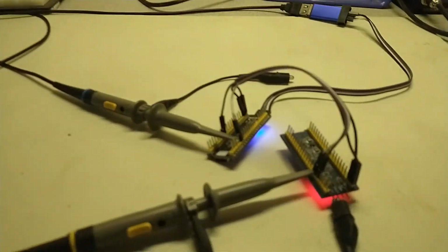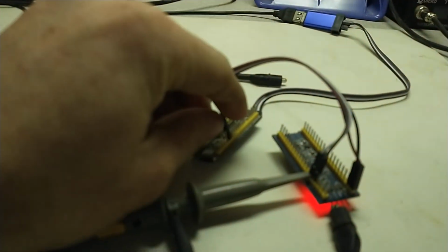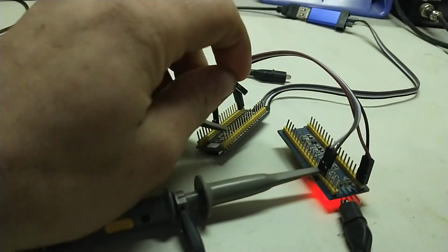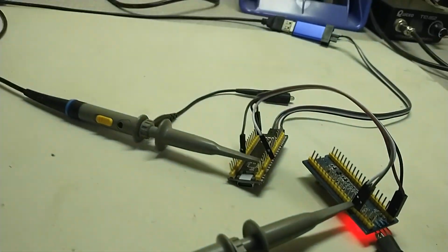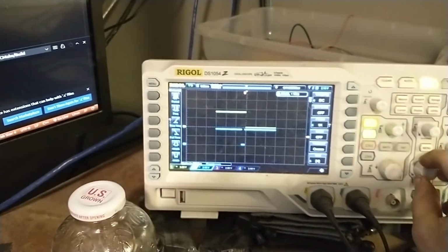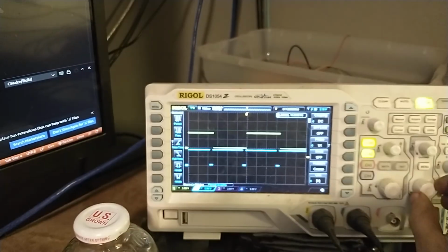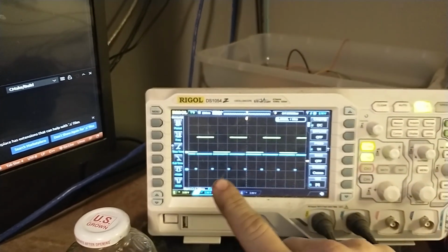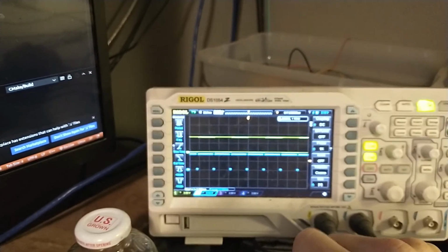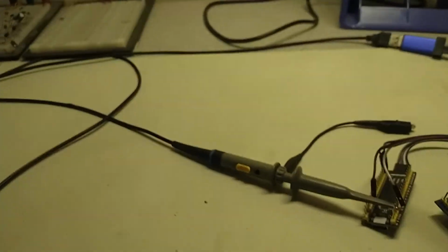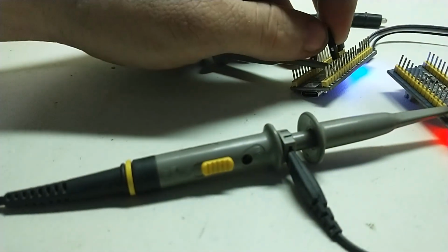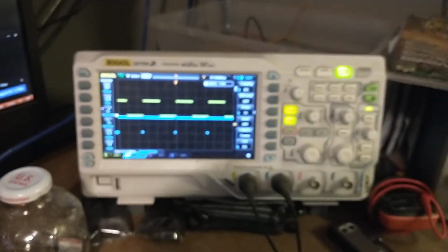The other nice thing is, if you lose the cam sensor, so I'm just going to pull that out, like you lost your cam sensor, then you're no longer able to do sequential. You can see that is happening up here. We're doing a wasted spark. So it's some fault handling. If I plug this back in, you can see we go back to sequential timing.